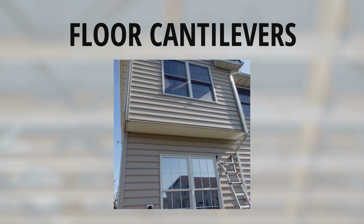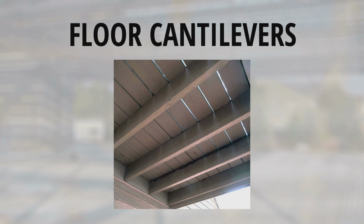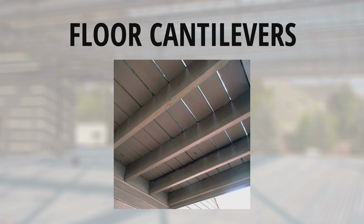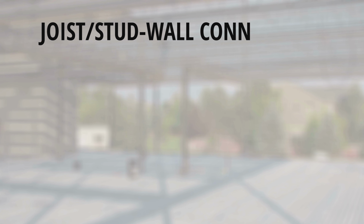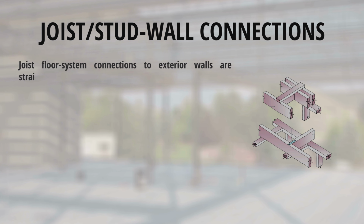Mudsill, first floor framing or double top plate, second or subsequent floor framing. Double joist in sides of cantilever. Extend the cantilever joist twice as far into the building as the length of the cantilever. Joist stud wall connection. Joist floor system connections to exterior walls are straightforward.